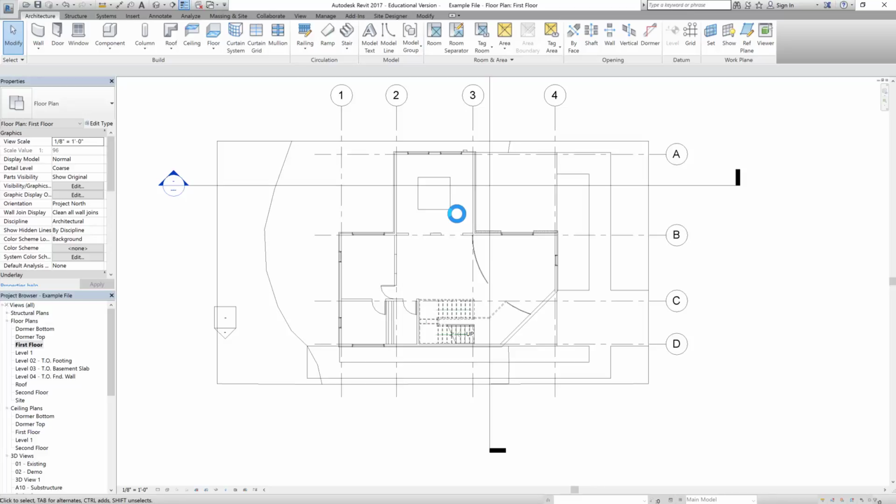They don't want to copy it, because just in case this model is changed by the architect, then if they copied the model, that change will not reflect in the copied model. On the other hand, if they link the model, in that case, if there is any change by the architect in this model, it will be reflected in the linked model. So they will know in real time that something has changed. So that's the reason, when we model MEP, we'll be linking this architecture model into our new MEP project. So before we do that, let's close this.